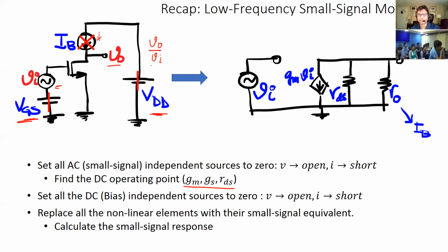And from that, you derive the small signal model like shown here. Essentially, you substitute all the small signal models. In this case, it's pretty straightforward. If you had a current source like a current mirror, you would put that current source's small signal model as well. As is shown here, gm and the RDS for the MOS transistor, and this R0 is basically the output impedance of IB. Although it is open, you still have a small signal model for it, which goes in parallel.